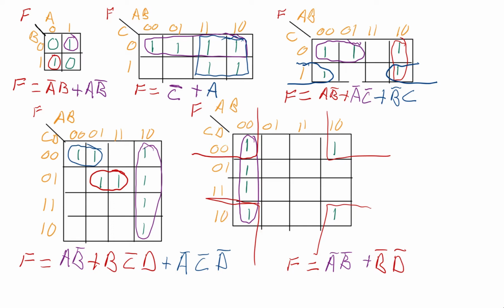Now, one thing that I'll point out on these K-maps, notice we swap the 2 columns. It goes 0, 1, 3, 2. Also going up and down, we got 0, 1, 3, 2, and we swap that. If you do not swap it, these K-maps will not work because two letters would change as we moved across here and as we moved across there. So hopefully that's a good summary on how you can use K-maps.